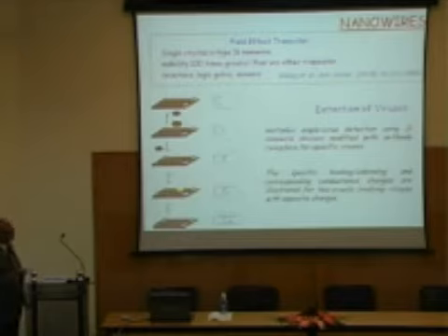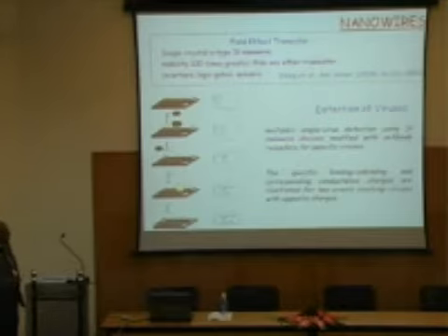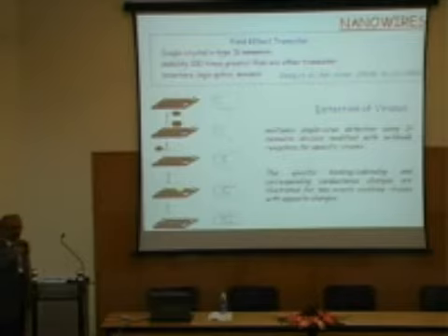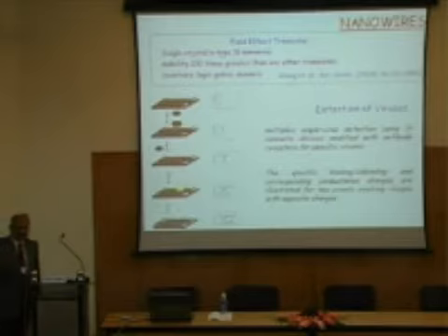And other than in electronics, it has a lot of role as a sensor. It's a biosensor. And there is a lot of work on silicon nanowires, how you put some antibodies on the nanowires and you can detect viruses and other pathogens, etc. What you do is you measure the conductance of the wire with the pathogen, without the pathogen, and that gives you a signal.